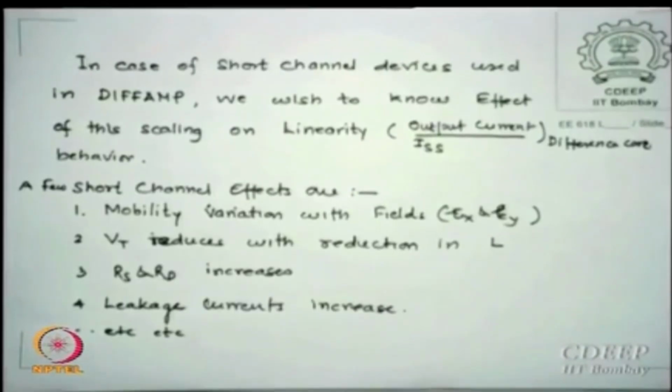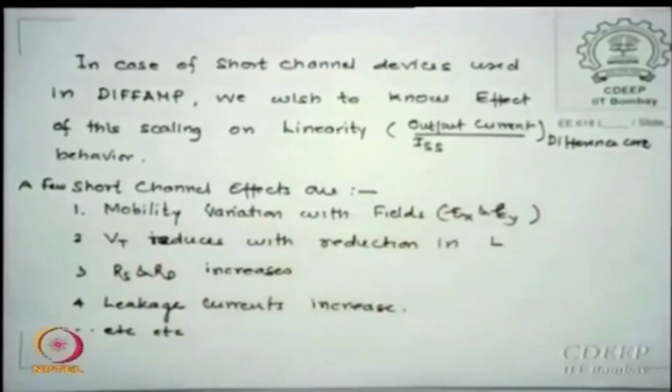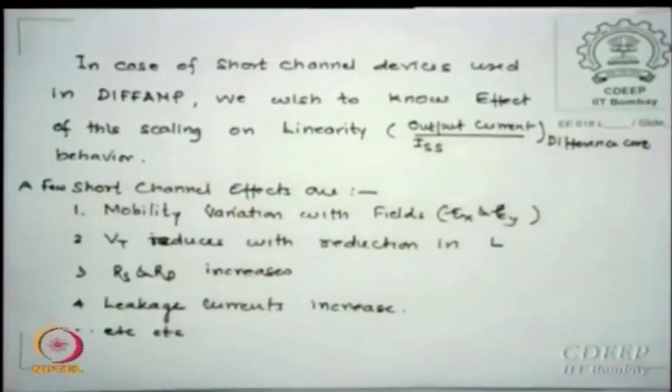So of course there are many more short channel effects. Right now I specified this. From the circuit point of view, even if it reduces I know how much, mobility changes I know for that how much, so I am not worried too much on them, I am designing with base. But this is something I have not earlier calculated, now I may have to. See, remember mobility and Vt's are still difficult values, but they will be specified for a node, okay, which is not in my hand, but I know, okay, I have to work with this.